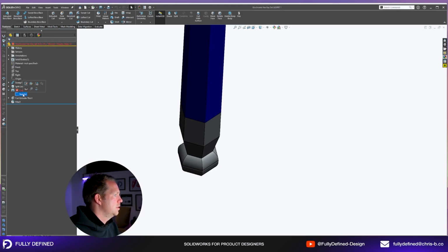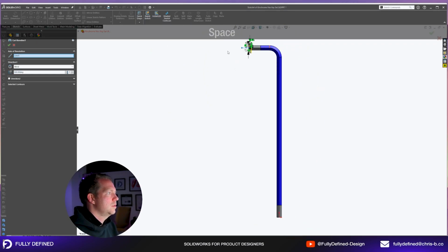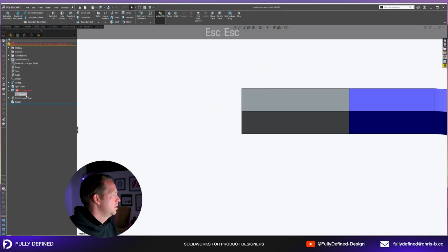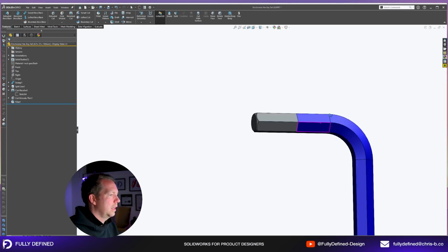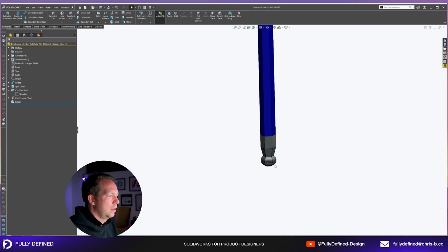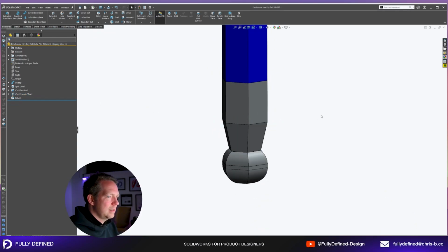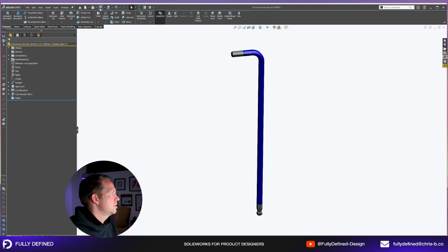And now we can change this cut revolve. So this cut revolve, we're getting some issues because what was previously a 5mm width with a 4.7 diameter cut no longer works. So in this configuration, this sketch, we need to go to this configuration and we're going to -1. Okay, so that cut revolve now works. At the bottom, we're going to look at that detail, and in this example, we're going to leave that exactly the same. That may change as we go through the different dimensions, as we go through the different configurations.